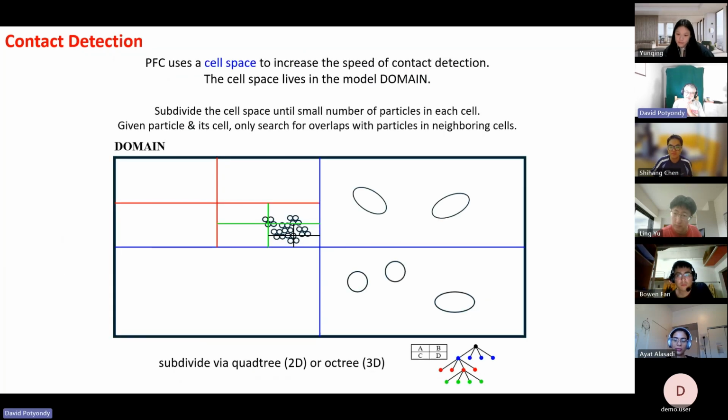One other thing that you should be aware of is what's happening here under the hood. The simplest possible way to make a discrete element program is to say, I have a particle, so you have a data structure that stores information of the particle. Some of that information is things like radius and mass. Some of that information is velocity and position. It stores all that, keeps updating that. You need some graphics that can draw that stuff, right? And you need to have some method of finding new contacts when they start to touch.